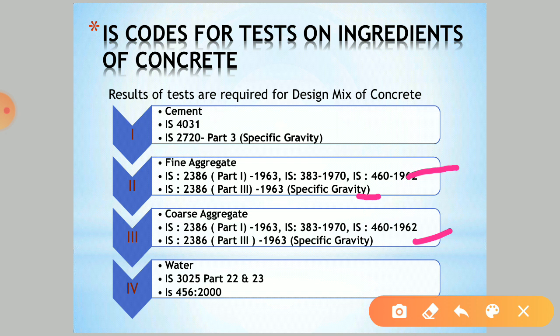Also, we should not neglect the water which we are using, because if the chloride contents or impurities are more, then there will be degradation of concrete and it will not satisfy its durability criteria. You may have seen cracks or white spots, or spalling of concrete. It is because the water used may have some contaminants like chloride.